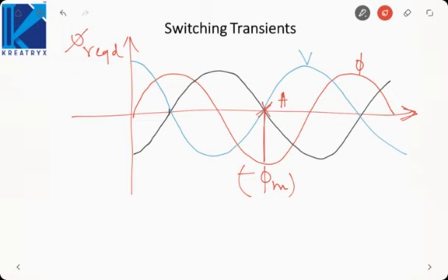But when the transformer was switched off, there may have been no flux inside it. Because the transformer is off, there is no current, hence no MMF and no flux. During the switch off state, I can assume that the flux inside the transformer was 0. Though there may be some residual flux because we are talking about ferromagnetic materials, still I am making an assumption that the flux was 0.